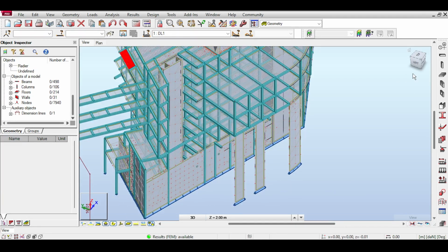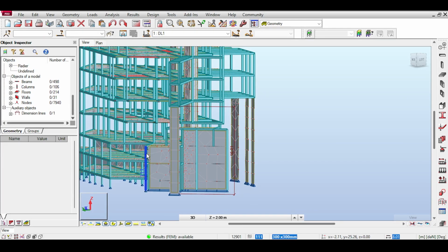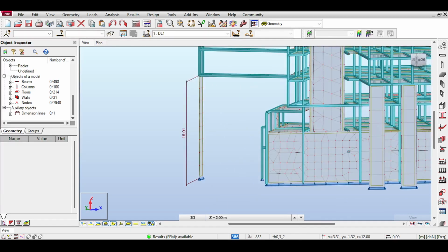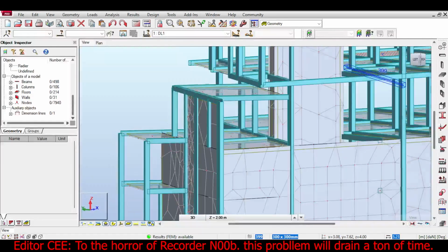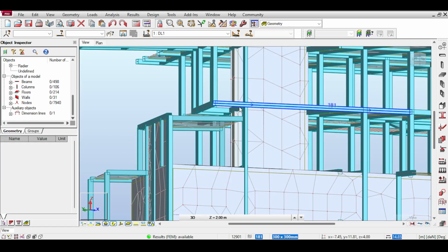Similarly for those three walls. Is there anything else where buckling might be a factor? Yeah, this column is still something I'm worried about. Those seem to be fine. So yeah, I think the sections... Wait, is this a column just floating in midair? Oh, there is a column floating in midair. So I'm not happy about that section.